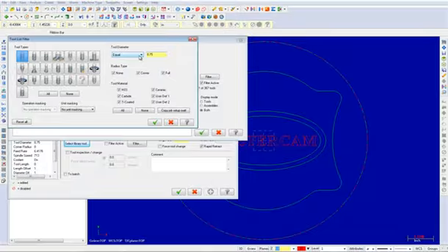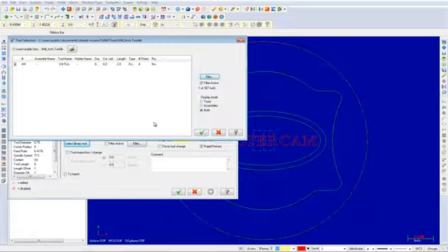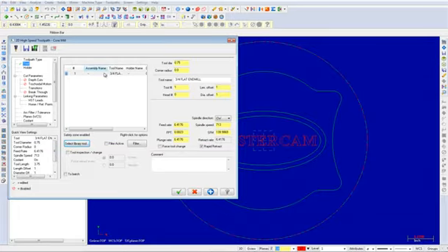Once complete, select the OK button to exit the Tool List filter. In the Tool Selection dialog box, you should now only see a 3/4 inch flat end mill. Select the 3/4 inch flat end mill and then choose the OK button. Your tool will appear as shown. Input the following comment: machine the elliptical shape boss. Once you have entered the comment, select the cut parameters.